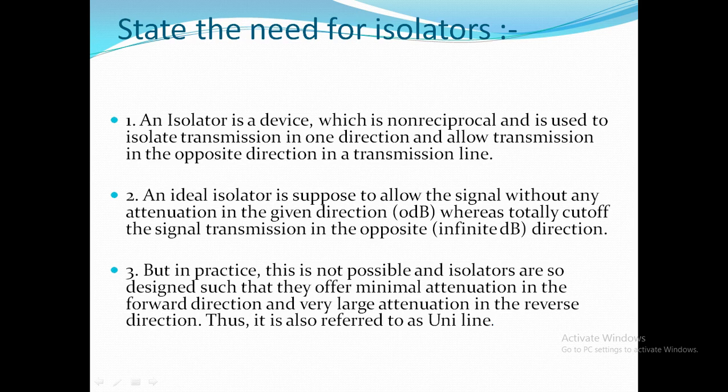Whenever an unmatched load is connected to the waveguide, reflected waves are generated from the load and returned towards the generator at the other end of the waveguide. Due to this, the frequency stability of the generator will be affected. In order to minimize the frequency instability, isolators are used.